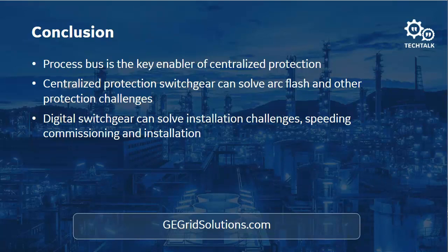In a switched Ethernet process bus, what that looks like is each of the centralized protection units, each one of the B30s, is connected to the switched Ethernet network, and they're subscribing to all the MU320s. So redundancy in these centralized protection schemes is actually easier to achieve than the redundancy that we would need on a traditional process bus scheme.